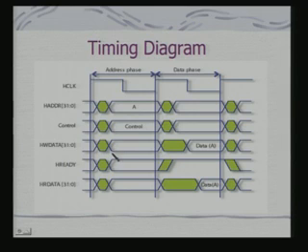If it is a write operation being initiated by the master, the data should be available at this point itself. And when there is the HREADY signal, depending on its status, wait states will be introduced. So, in this case, your data is delayed. I introduce a wait state over here. Similarly, for the read also, the data phase will get delayed.